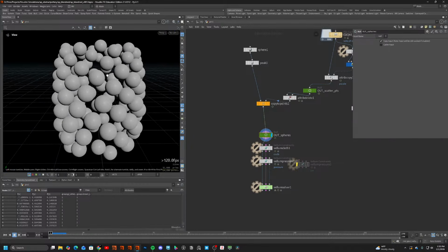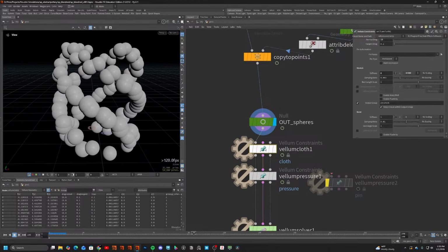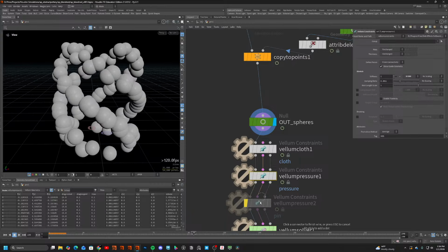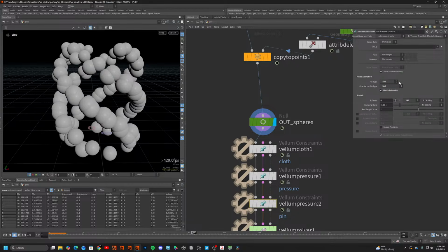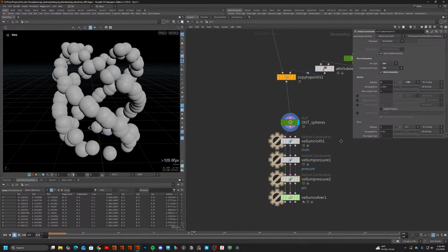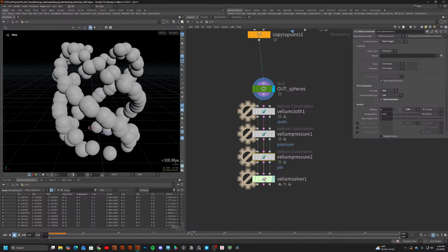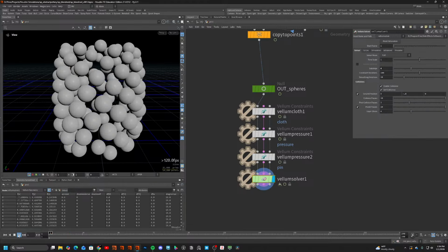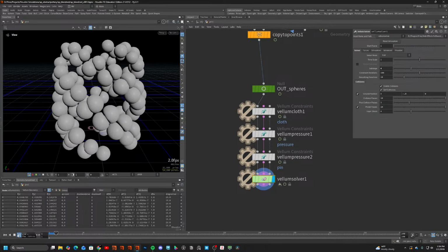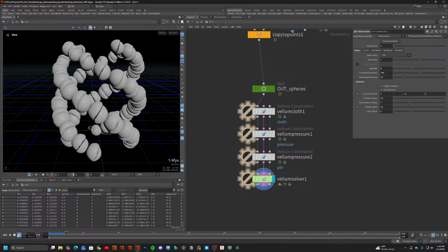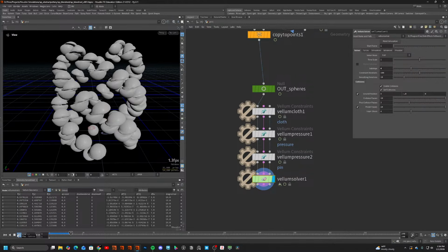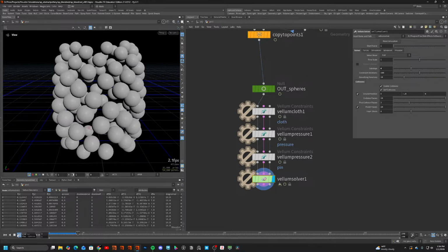So what we have, our spheres rotating here. Then we just need a pin constraint and say that they need to be soft so they can still move but match the animation. It's always a bit playing around with these values and also your substeps and stuff. But let's see. Okay. What is going to happen? Ooh, nice. It's going a bit too flat to my liking.